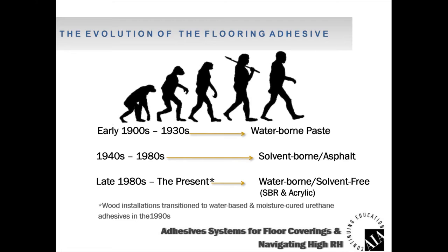Your traditional cutback adhesive is a solvent-borne asphaltic material. It got its name cutback because many years ago they used to take that asphaltic material and cut it back with gasoline, stuff like that. It got its generic name as cutback. It just kind of stuck with the adhesive.